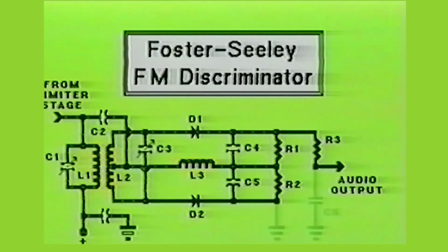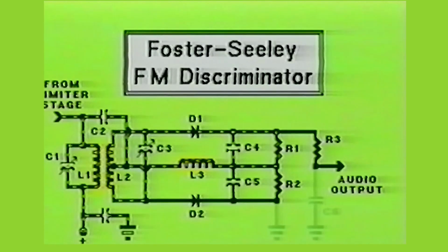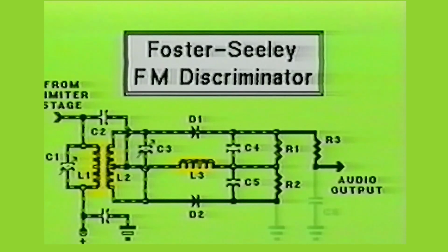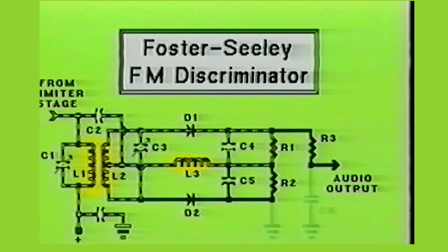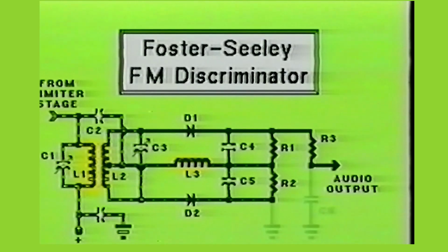Since ES1 and ES2 are no longer equal in value, the current flow through the top and bottom parts of the circuit will no longer be equal. Since ES1 has the greatest potential, resistor R1 and diode D1 will conduct the heavier current flow. This results in the voltage drop across resistor R1 being greater than the drop across resistor R2. The net result is, the output of the discriminator circuit will be a positive value.